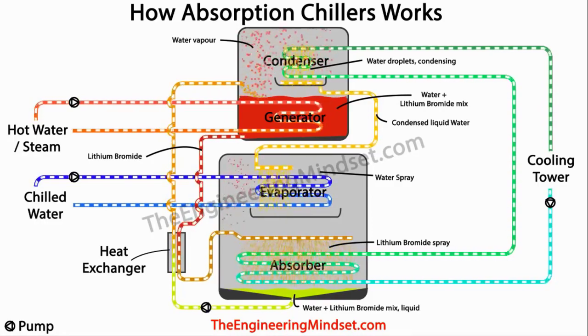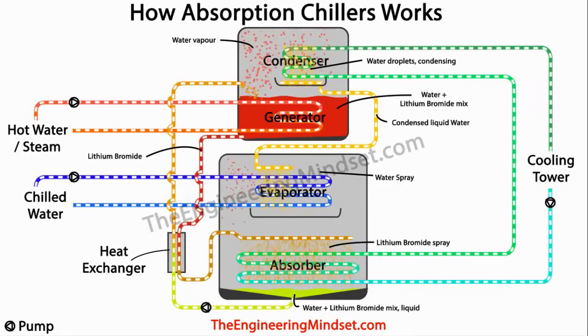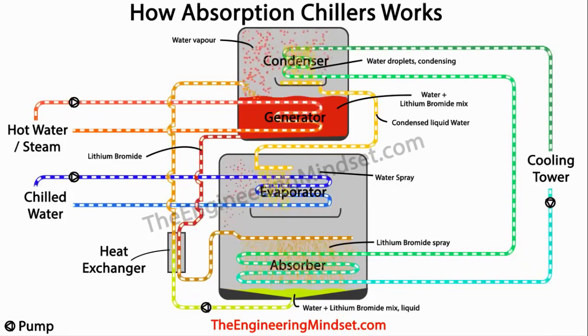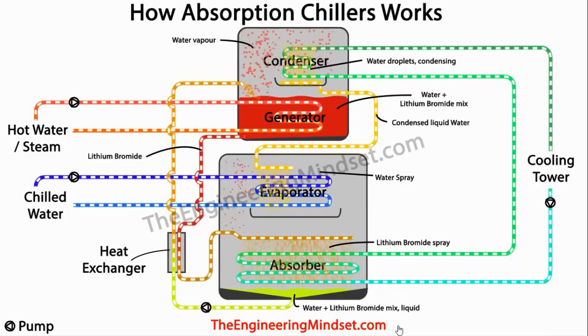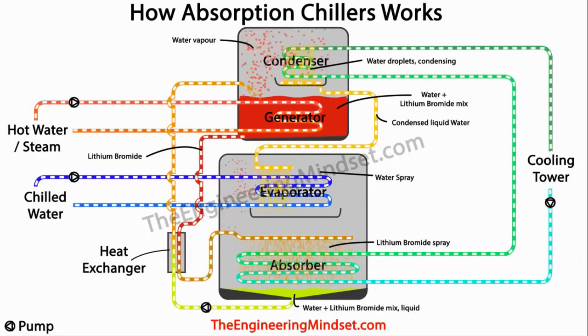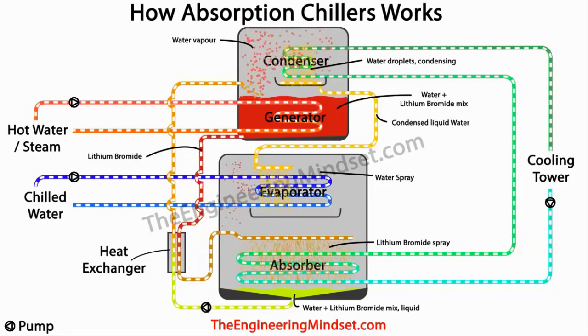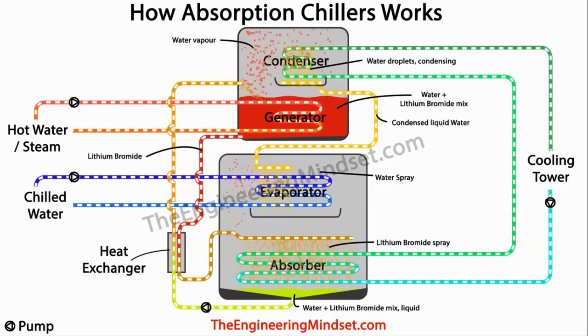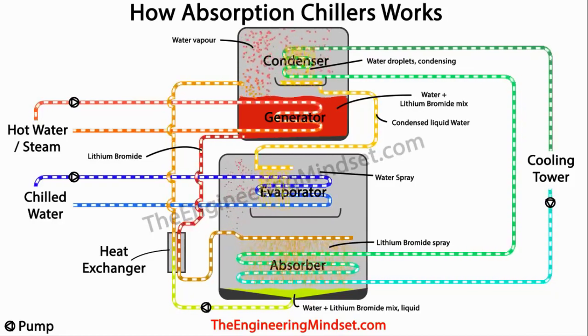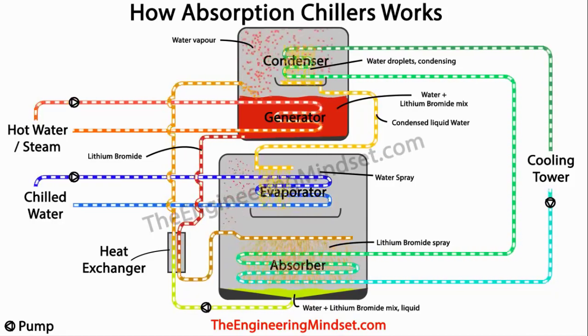The chilled water will enter at around 12 degrees Celsius, 54 degrees Fahrenheit, and this will transfer its thermal energy, its heat, all the unwanted heat from the building. It will transfer that through the tube wall and into the low temperature water film, which was sprayed across the outside of the chilled water tubes. Remember, the two waters never mix. They're always kept separate, and they are separated by the pipe wall.